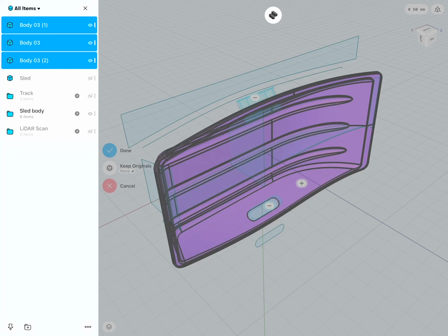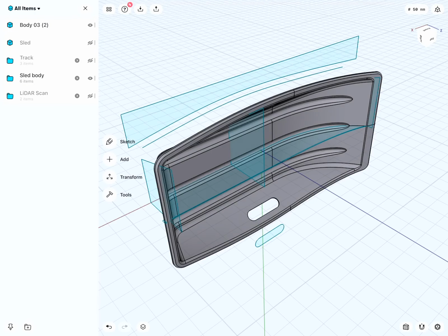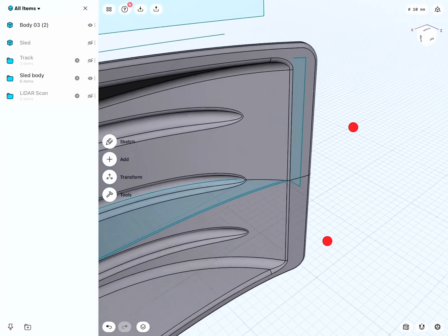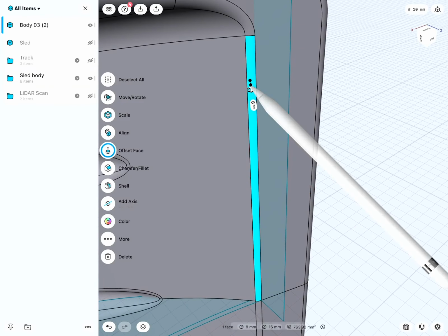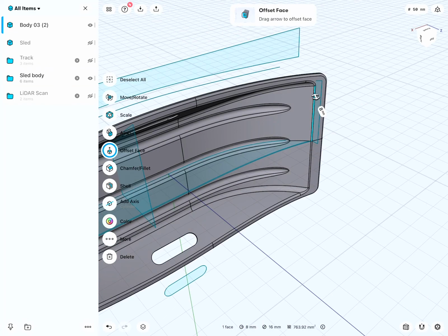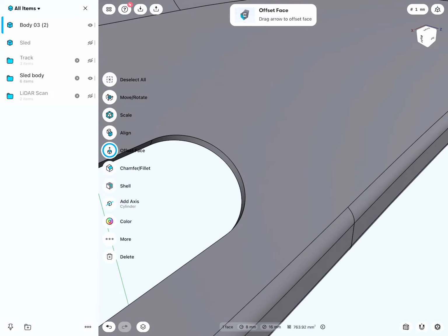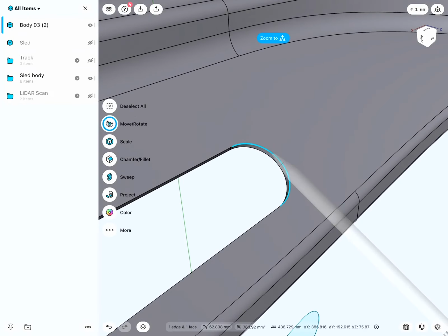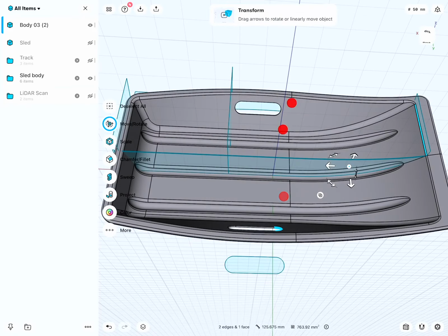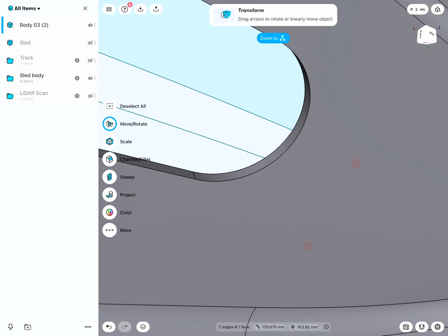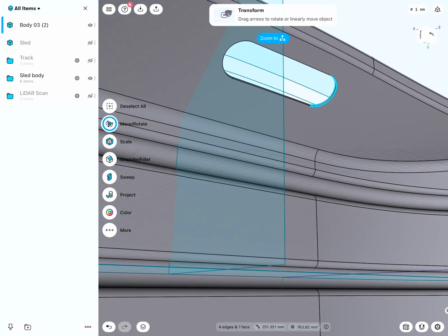This is also a little tip now. So you see that the calculation takes a little bit. The main reason for that is all the fillets I added. So ideally what I should have done first is maybe add a fillet, like all those I added it here. But when I'm not really done yet, I should have removed them. So when I then go ahead and do these calculations, it's faster for the software to calculate. And that's simply because the fillets add more surfaces. Makes everything more computationally intensive.